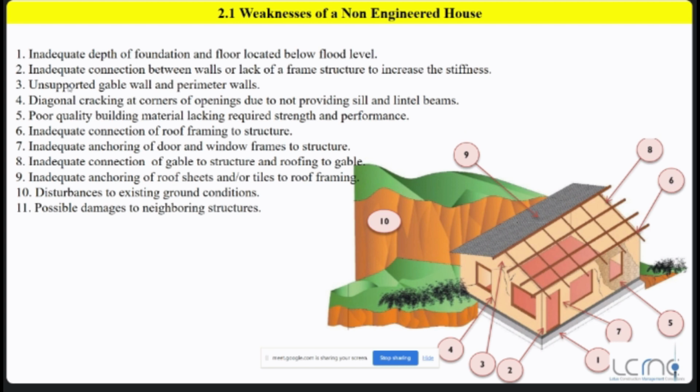Let's say it exceeds in height. If it exceeds in height, then what do we do? Exceeding in height also means exceeding 9 m², so you cannot put a stiffener column there. Separating it with a vertical element makes no sense. So you need to provide a stiffener beam, that means a horizontal beam along the wall. So definitely the area will be divided, and your 9 m² will be coming up. So that is how you need to increase your stiffness in the walls.